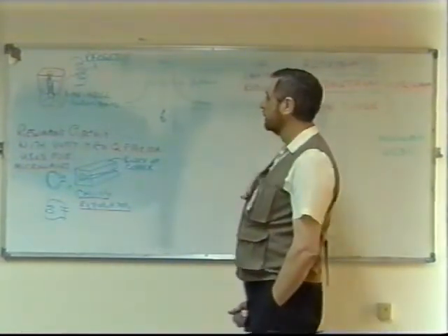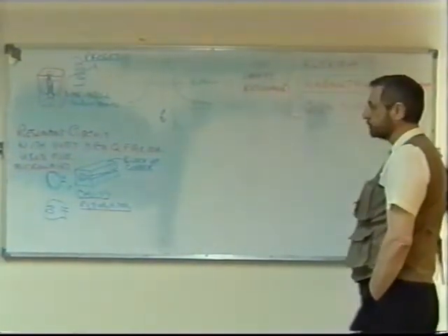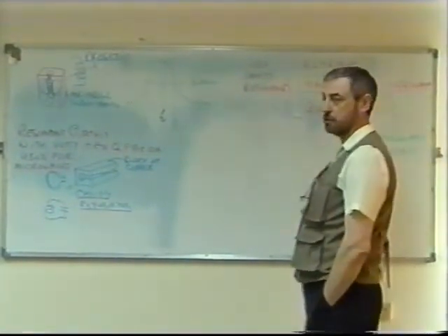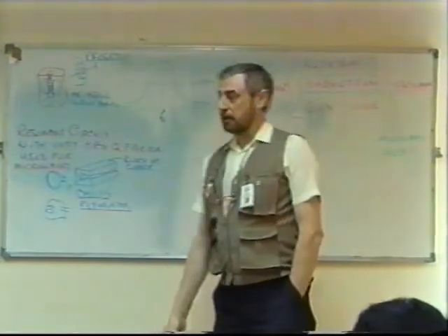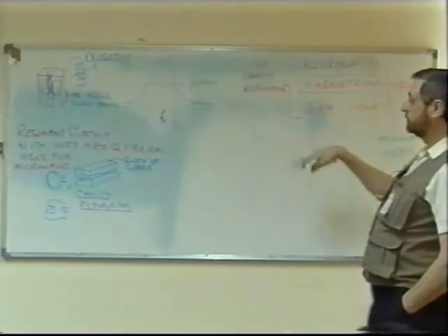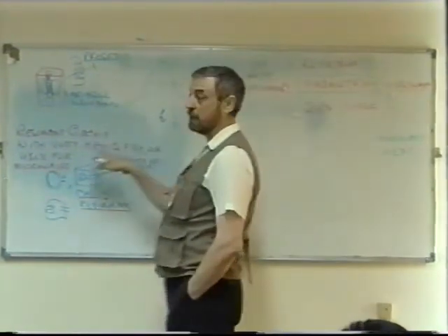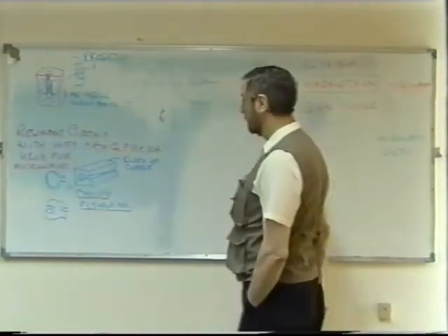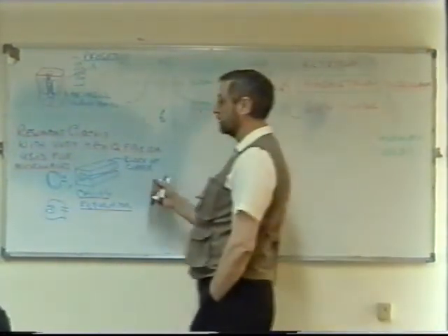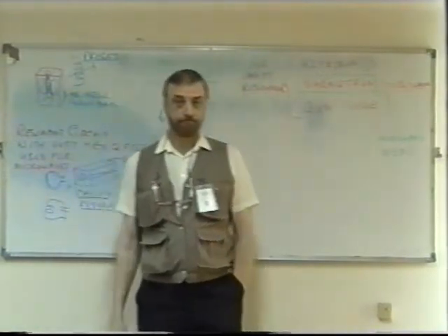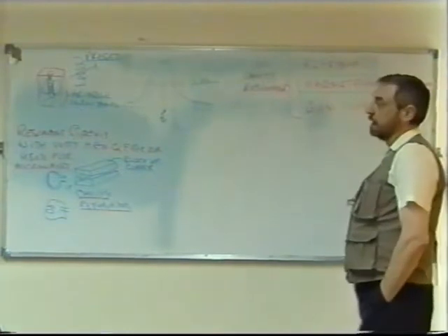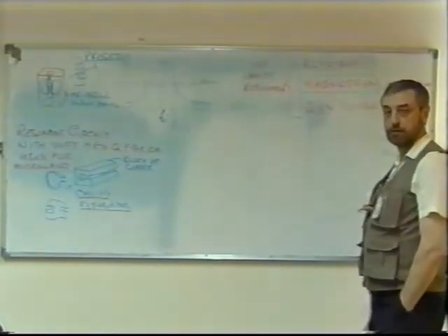Basically, we covered tuned circuits so that we know we need tuned circuits for radio frequency generation, to generate radio frequencies as oscillators. Now, in the case of frequencies in the SHF band, when we're talking about the microwave region, we use special types of tuned circuits called cavity resonators, because the normal inductor and capacitor would not be suitable for too large values.